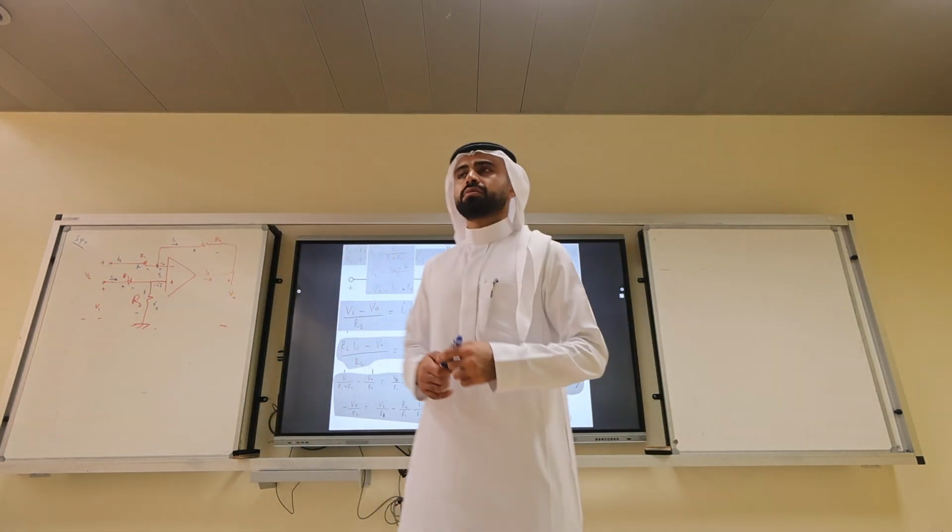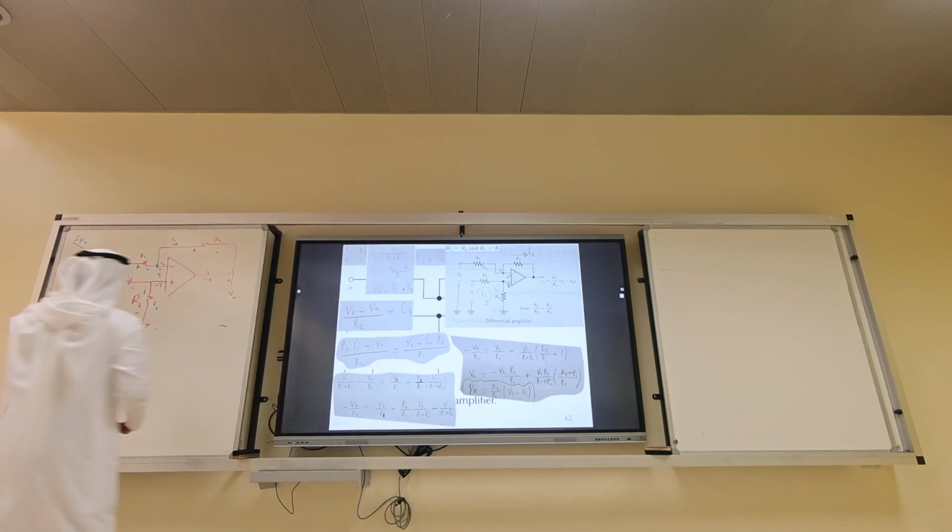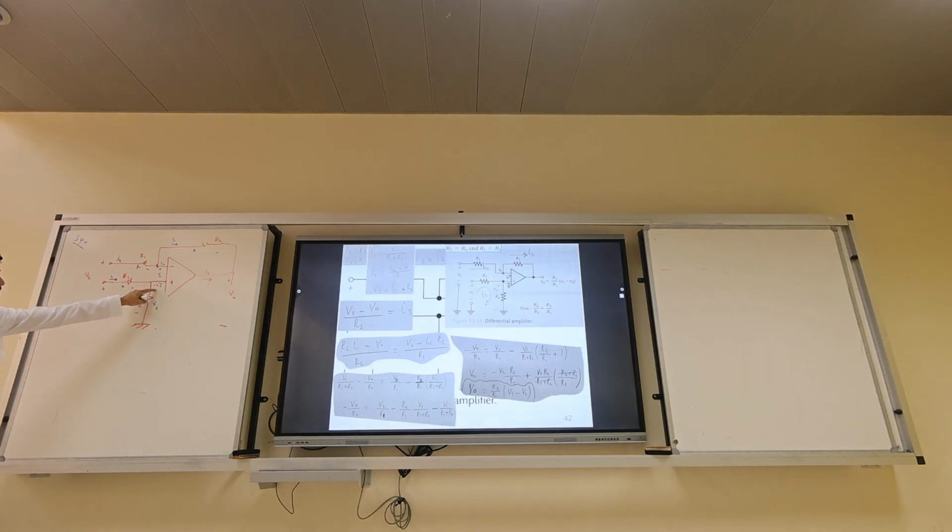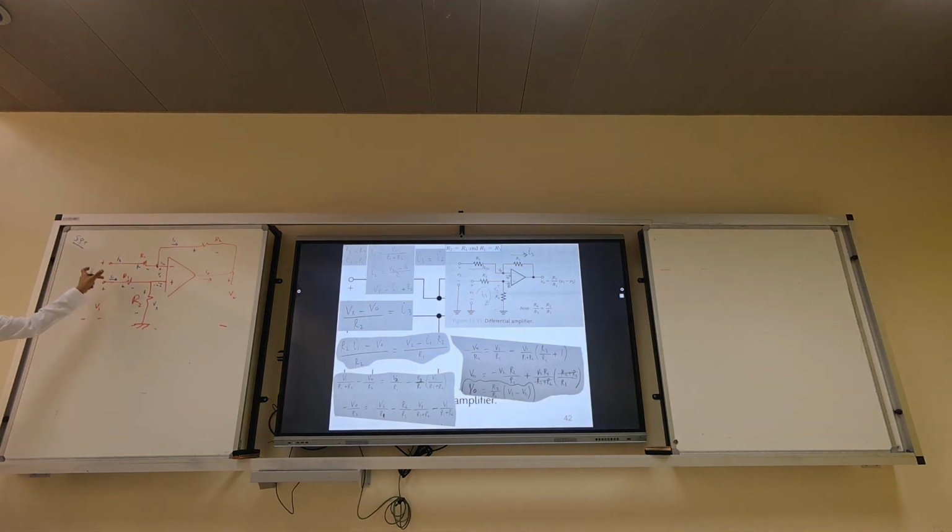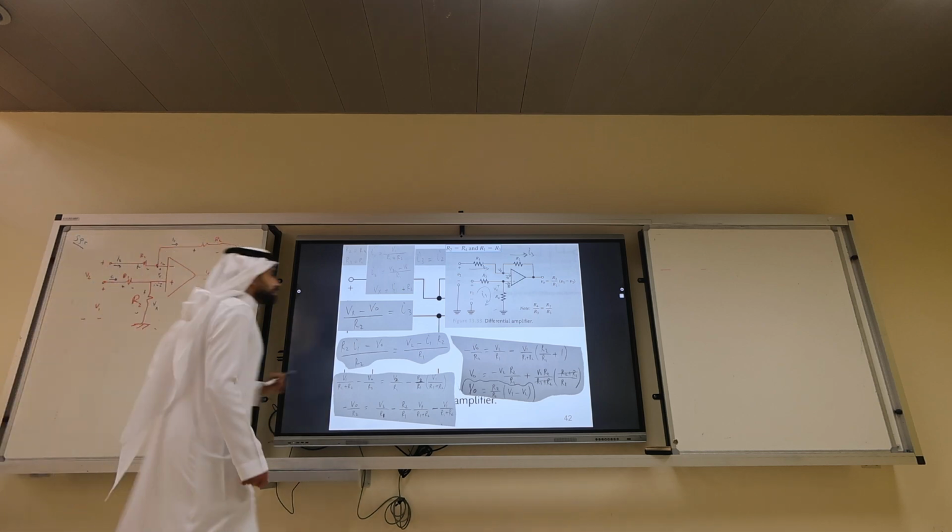How do we start? We need to think. How many inputs do we have? We have V1 applied to R1 and R2. I here is 0. So R2 over R1 plus R2 will appear here. Voltage divider rule. Get it? So R2 over R1 plus R2 times V1 will also appear here. In addition, we have a current I2 moving here, which is equal to I3. So let's analyze this circuit. I will start with V1. So what is Vx?